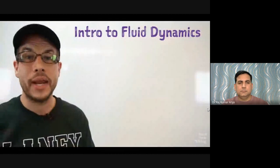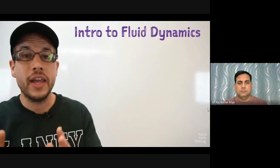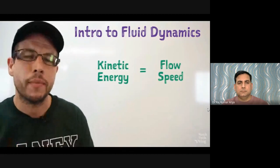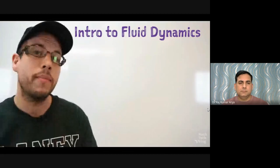Now, the increasing area of the volute chamber is essential to the function of the pump because that's how the pump develops pressure. We've talked about how the impeller imparts kinetic energy to the pumped fluid. And when I say kinetic energy, think of it as the speed of the fluid flowing through the pump. But flow speed is only half the equation. A pump also needs to be able to develop sufficient pressure to meet the requirements of the system.